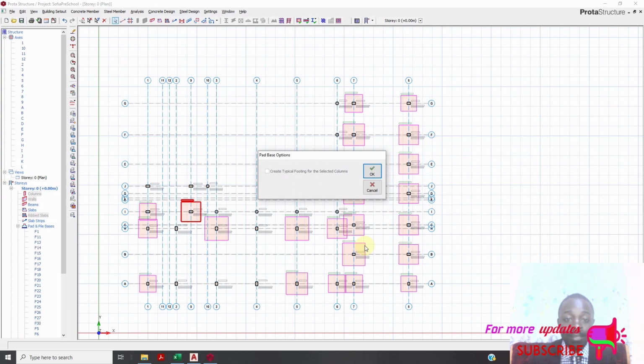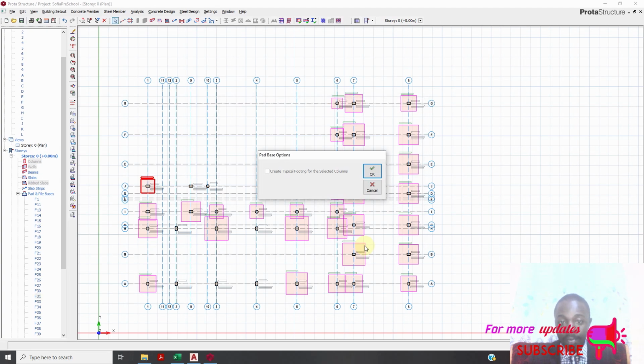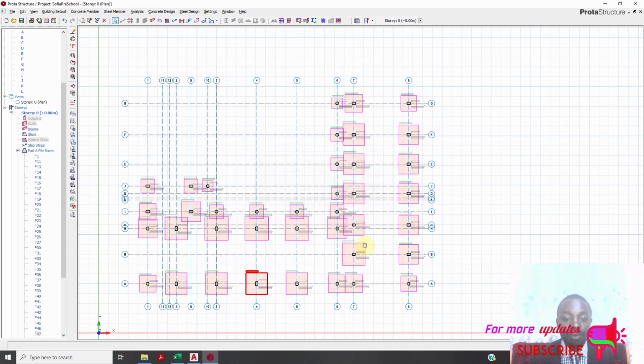The wall is supporting itself, and now the building is just supporting the slab and the slab self weight, its own self weight of the frame, that is the beams and the columns, and also the live load from maybe slab and extra dead load from slab. So let's see how our design will look, or what we'll get in terms of our design.